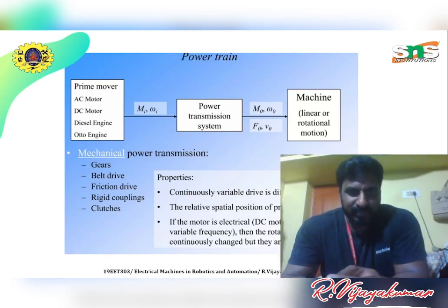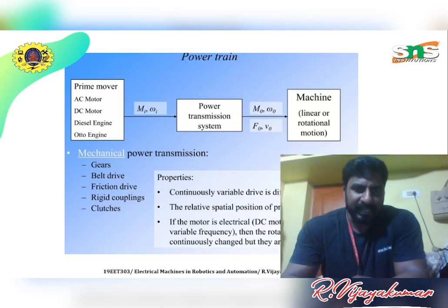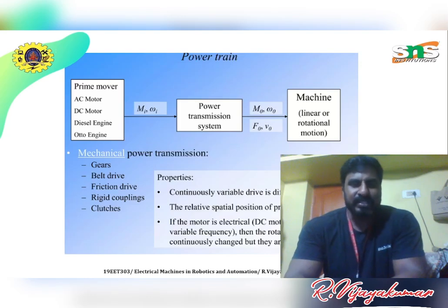Hydraulic is the best option for strength because the liquid medium used for the operation has a high mass density and is largely incompressible. This means that hydraulics can develop much higher levels of pressure and can use that pressure to transmit the power that will drive your applications. Industrial applications using hydraulic power may command anything from 1000 to 5000 pounds per square inch. So this is the important one.